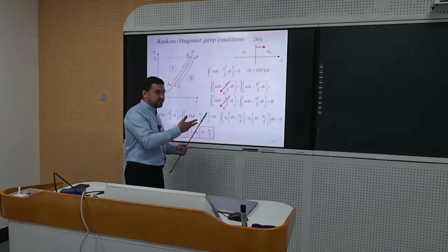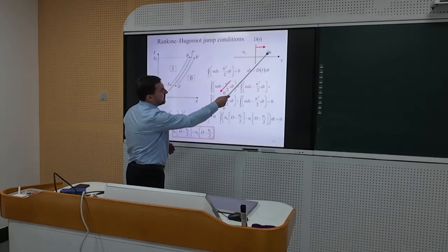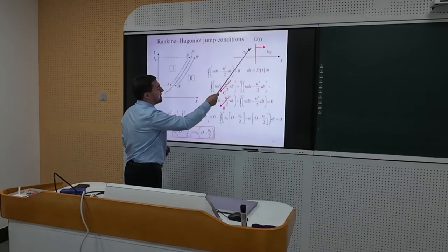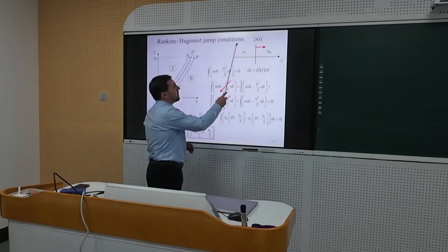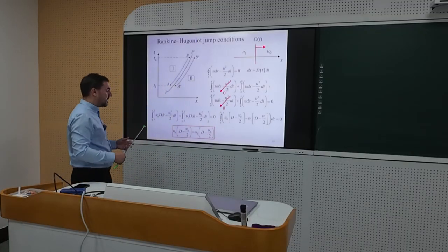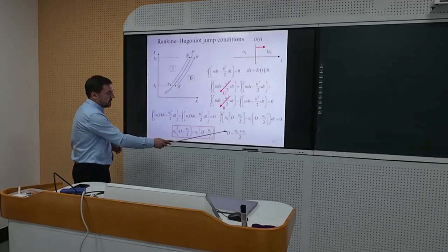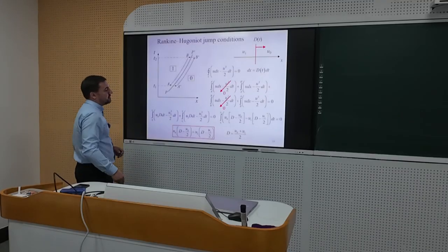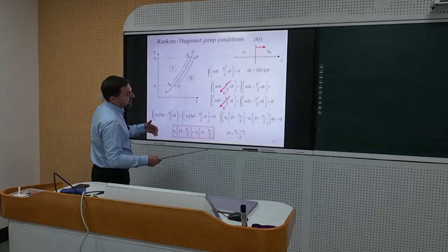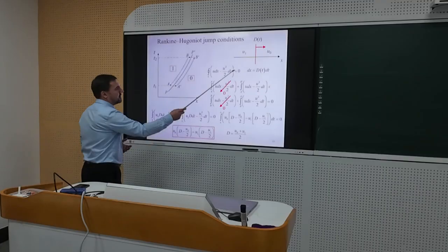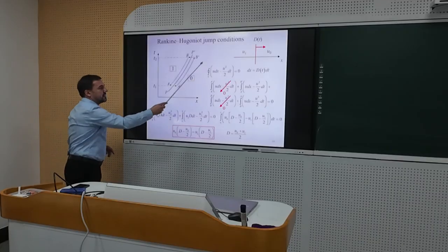In the same manner, we have such a situation in gas also. If you have density, velocity, and pressure in front of the shock wave, and some intensity of the shock wave, for example after an explosion or something like that, we can compute the parameters behind the shock wave. We can find D from this equation. D equals one half of u0 plus u1. So actually, it's just an average value between u sub 0 and u1. But once again, that's only for just one scalar Hopf equation.